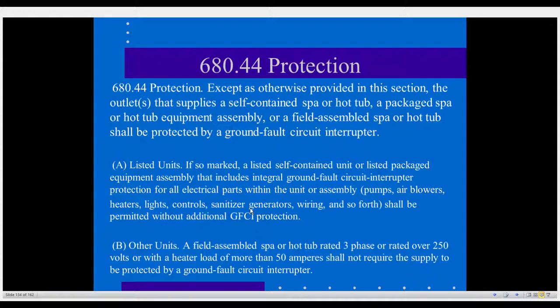A lot of times people will do this, and they'll install the receptacle, and it's further away than 10 feet, but it's in a way that it's maybe not GFCI protected already, maybe inside of a patio, outer covering, whatever. Let's see, I'm trying to come up with an idea. An enclosed 3-season porch, let's say, and they didn't have GFCI protection there. Or it wasn't required to have GFCI protection because it's existing and it's been there a while. Well, if it is more than 10 feet away, here it allows you to be able to use this application. All right? That's just some examples maybe when you might run into that application.